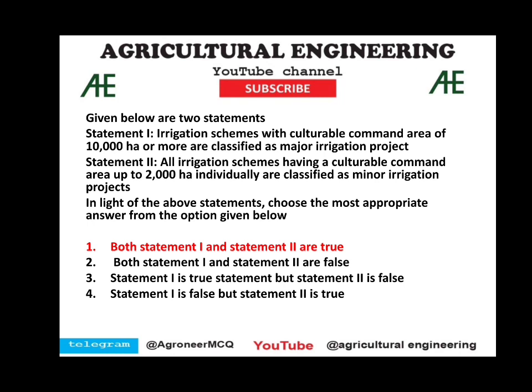Irrigation schemes with a culturable command area of 10,000 hectares or more are classified as major irrigation projects. All irrigation schemes having a culturable command area up to 2,000 hectares individually are classified as minor irrigation projects. You have to go through the classification of irrigation projects, only then can you answer this question. I will answer this: both statements are correct or true.